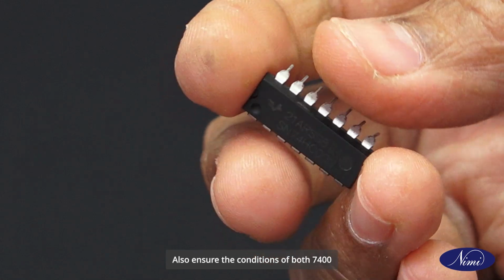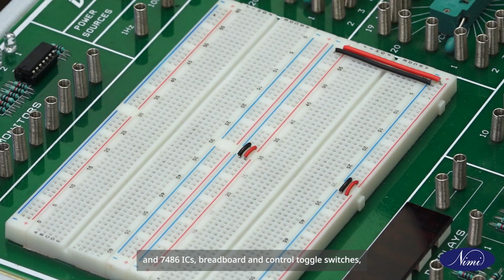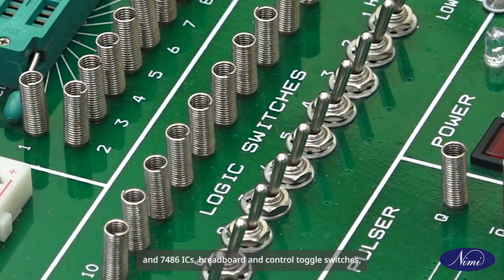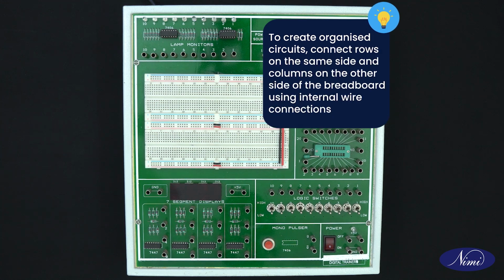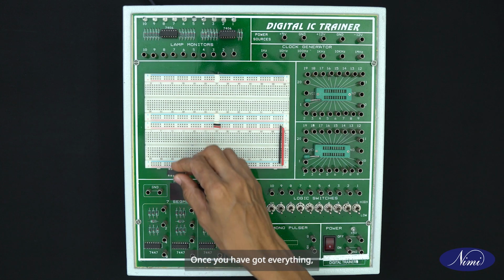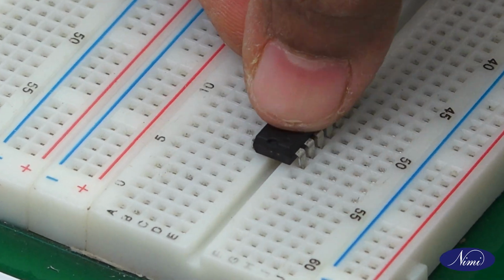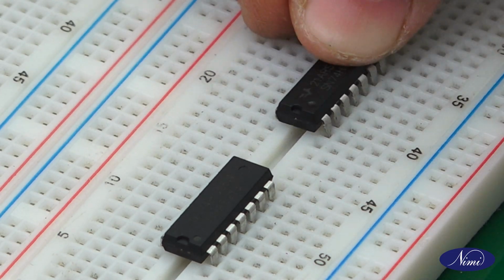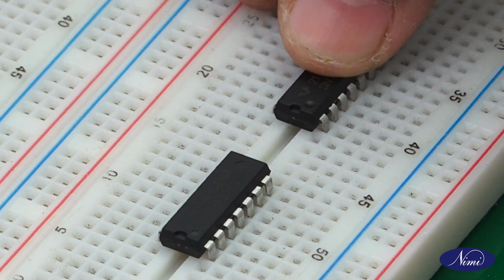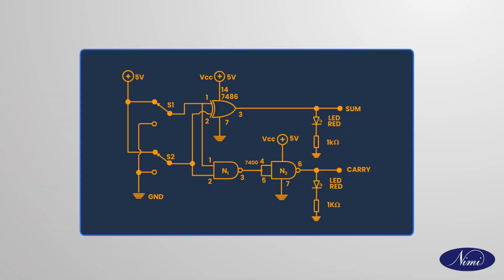Also ensure the condition of both 7400 and 7486 ICs, breadboard, toggle switches, resistors, and LED. Once you have got everything, mount both the ICs firmly on the breadboard. You can use the circuit diagram for reference.